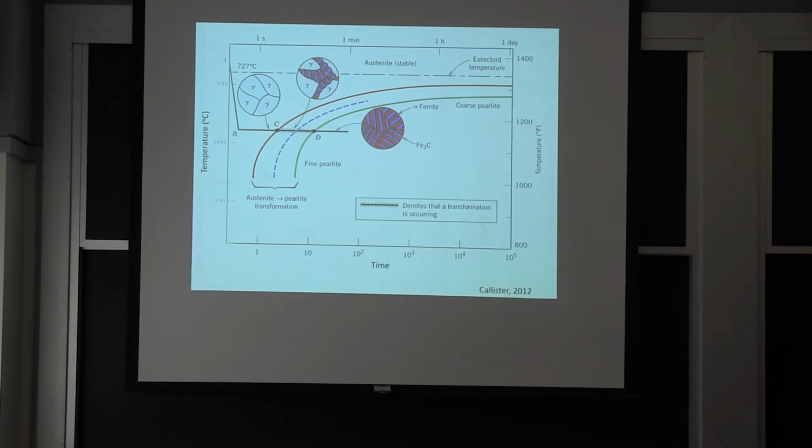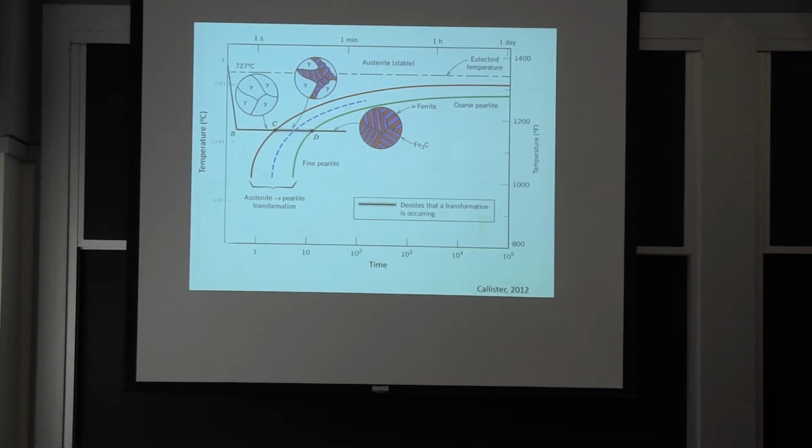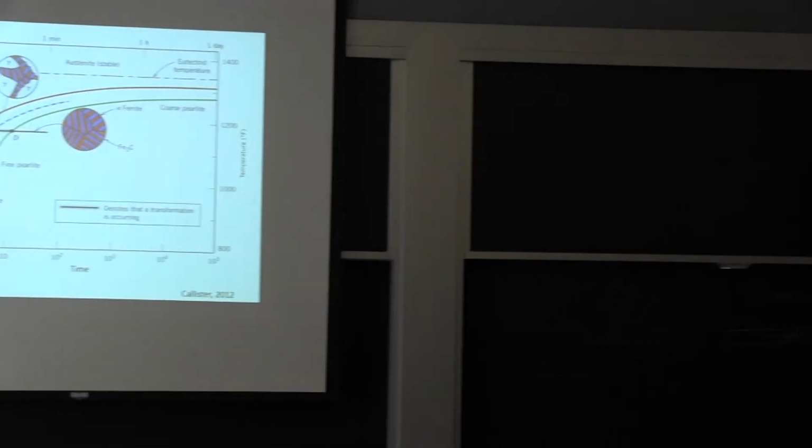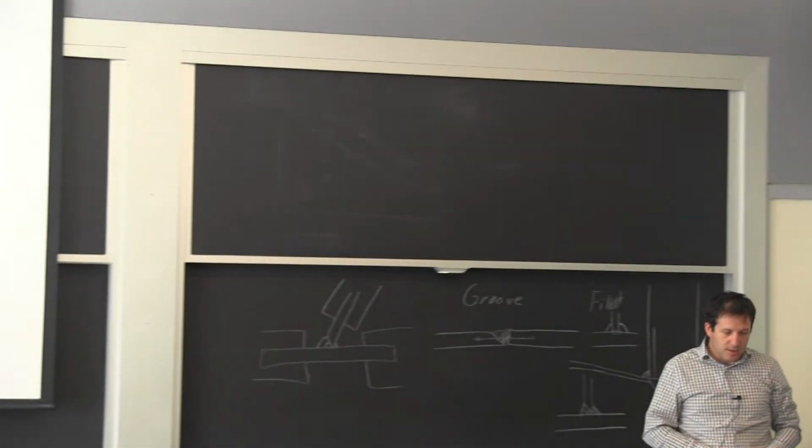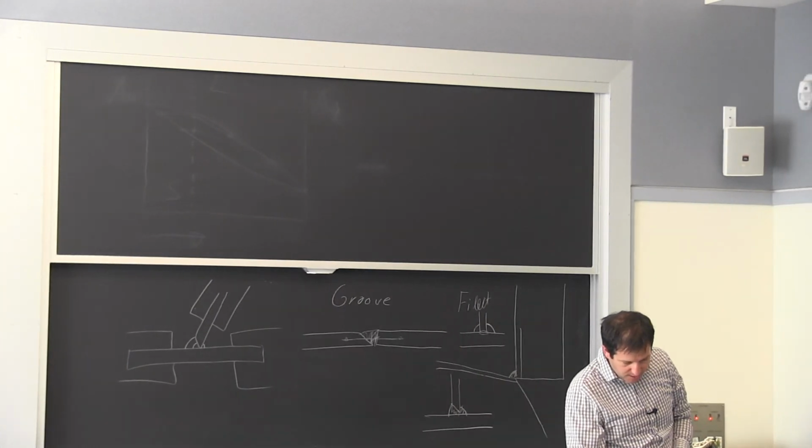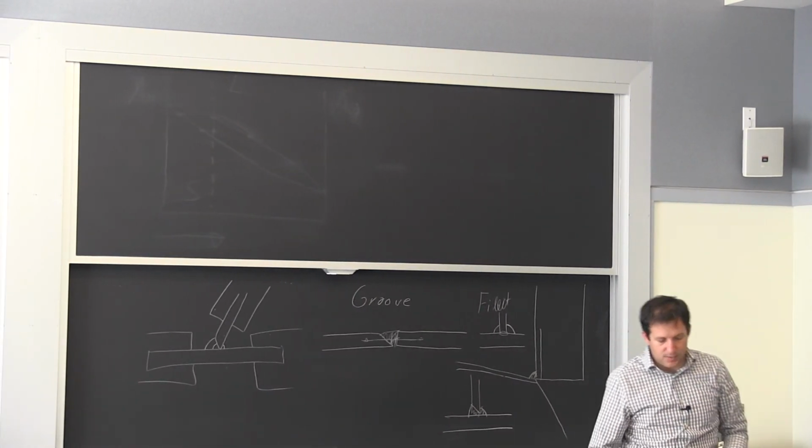This one here is the one where you're really controlling the temperature. There's another one that you can generate that would be based on more of a gradual cooling rate. So oven cool will tell you at what temperature you're actually going to form the different phases. The main aspect to this is to help you see why I am getting all these different phases.